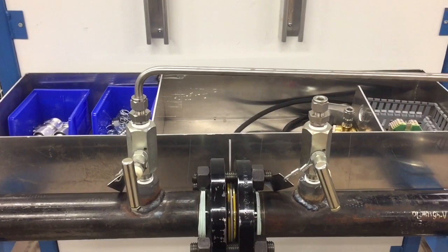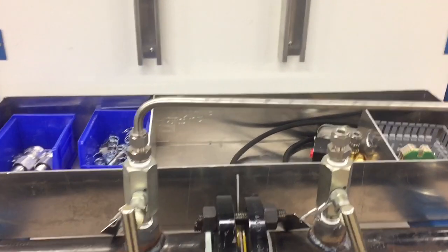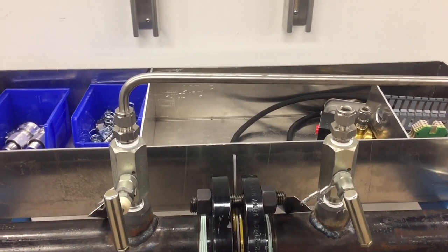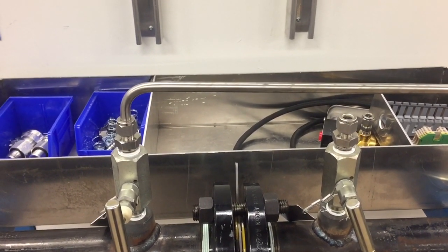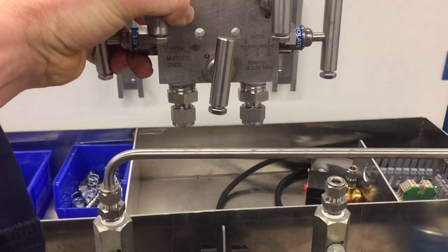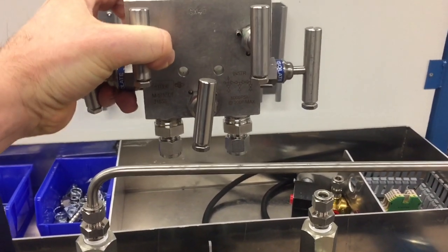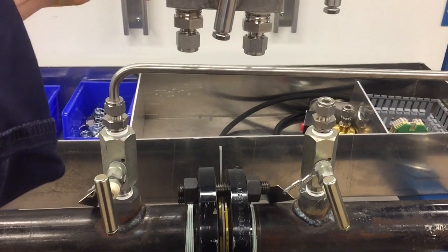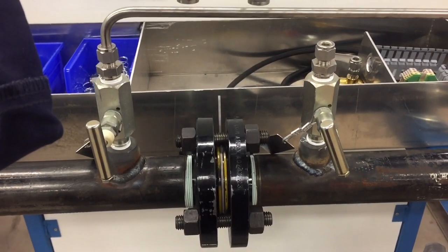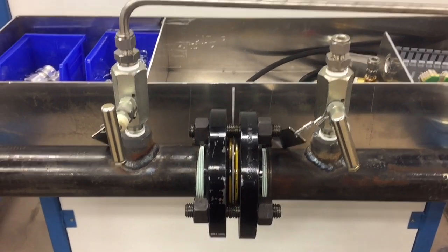Right, so I know our initial plan was to install the gauge first, but after bending our 90 there, I figured we'd make use of it, because we will need a 180 degree bend for our gauge, but I thought I'd make use of this 90 rather than just cutting it off. What we're going to be doing is installing our 5-way manifold here first. So we need to take the tubing right here and bend it up at a 90 degree bend. Our goal is to position this 5 valve manifold right above and centered with our flanged orifice plate.